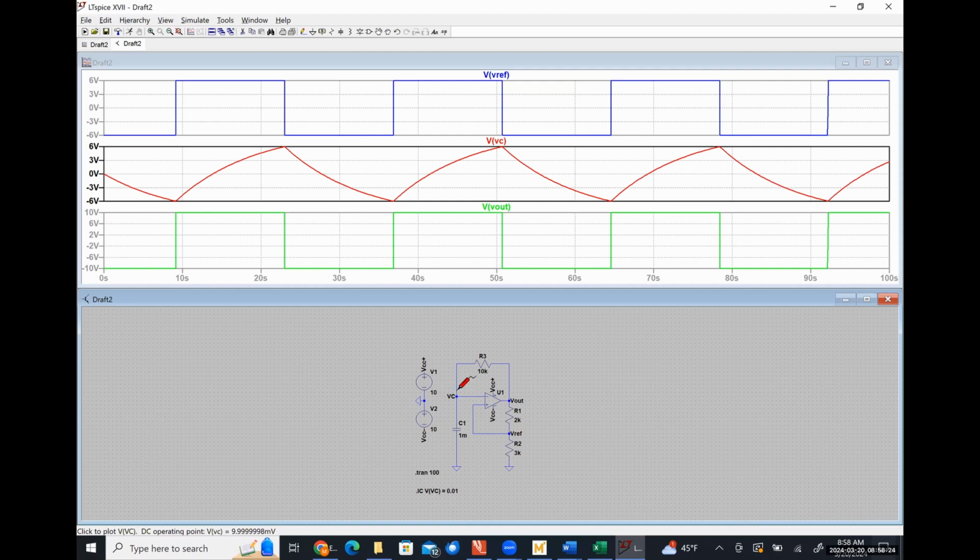So we were able to qualitatively describe what was going on, even if we didn't bother too much with all of the math in the background that's making it happen. So like I said, this is a way for us to effectively make a clock circuit. We can make it change from high to low at regular intervals. So we can use this as a timing reference for circuits that need a timer without having to deal with quartz crystal oscillators and all of that kind of good stuff. So just another application of positive feedback.